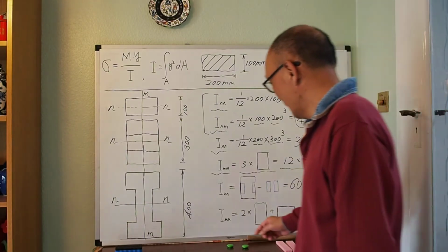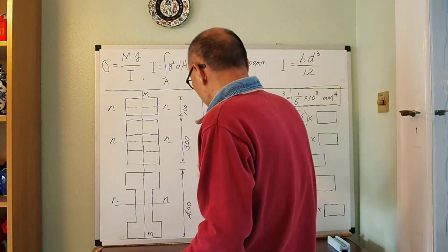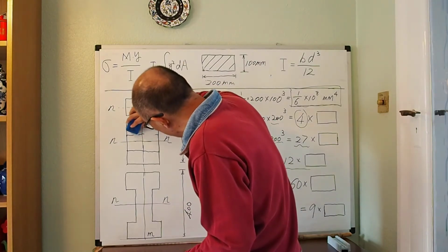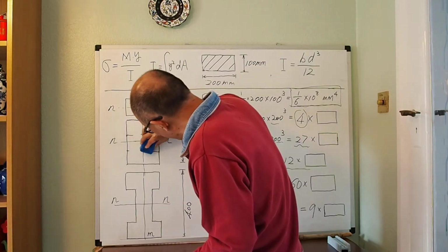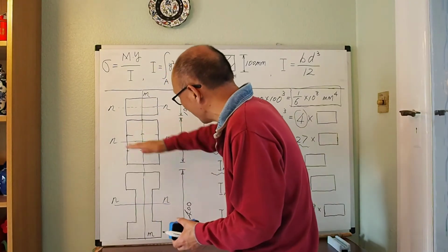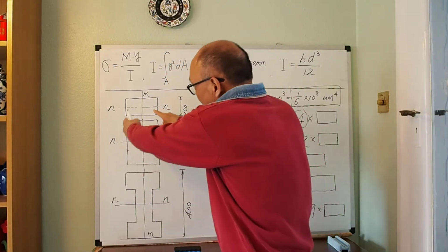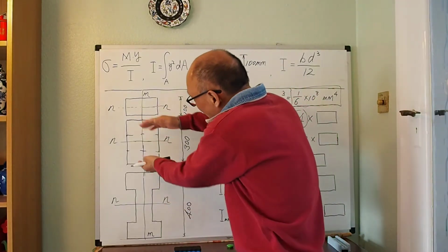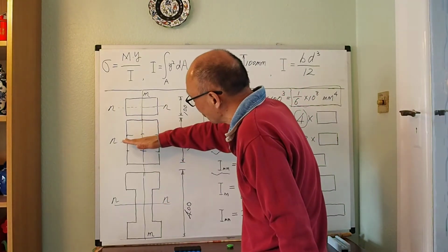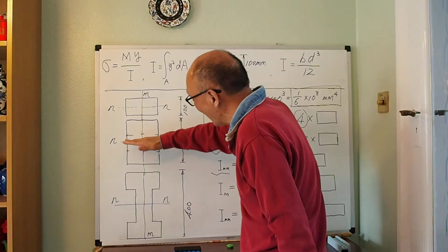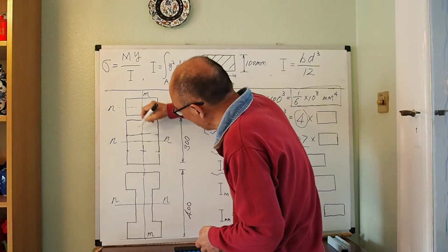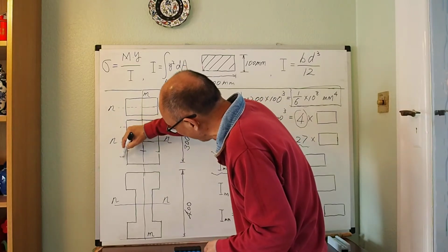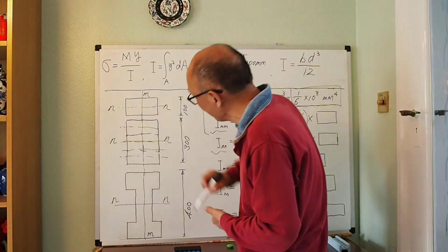Right? The difference between this one and the previous one, when we have the beam bending about that direction, is that by making this a solid cross-section, you force the whole beam to deform about this neutral plane, rather than each of them deforming about their own neutral plane.